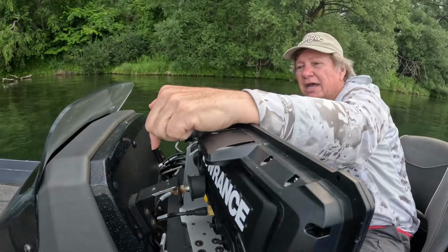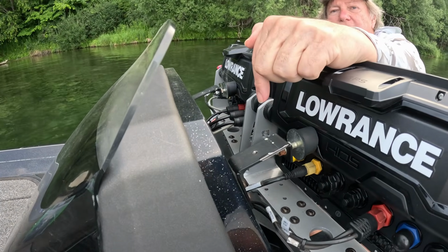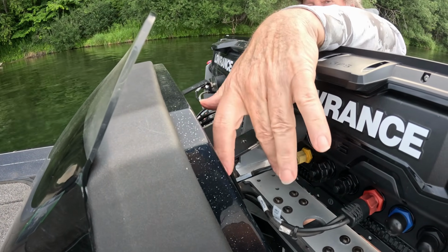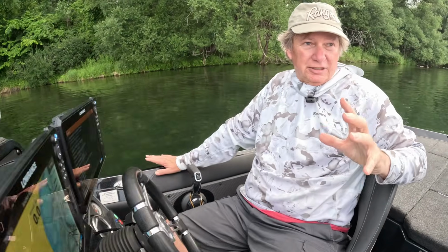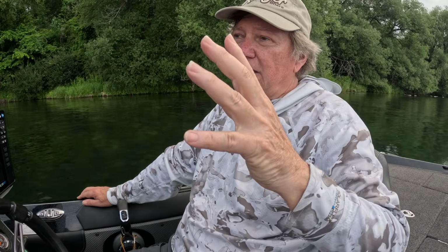All these units have 2 Ethernet ports on the back. You can see them down here, those yellow covers down there, okay? And what would happen is that depending on how it's configured, you may get a unit that would not receive waypoints from other units. It may not receive the map properly, so the fix around that is to put a network hub in, okay?